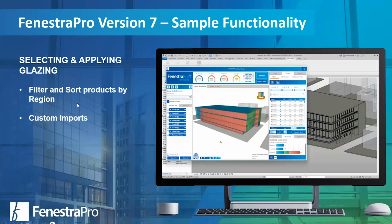Custom imports. So again, while we have our own glazing database, which is made up of predominantly 612 or 616 type of glass, you can also customize your own glazing within Vitro's Construct IGU or Guardian Glass performance calculator, and import that glass into the Revit model, where you can apply it then directly into the model itself.